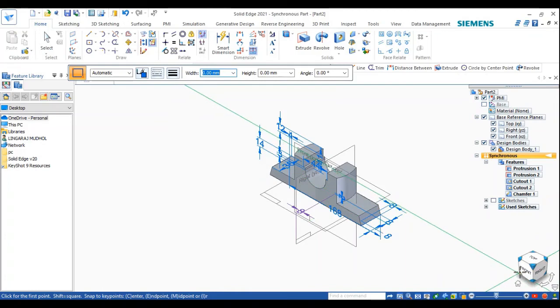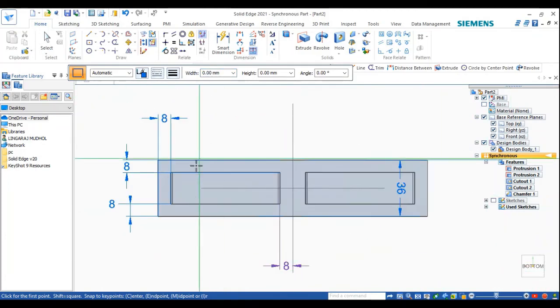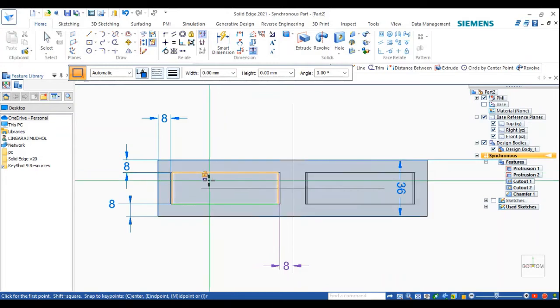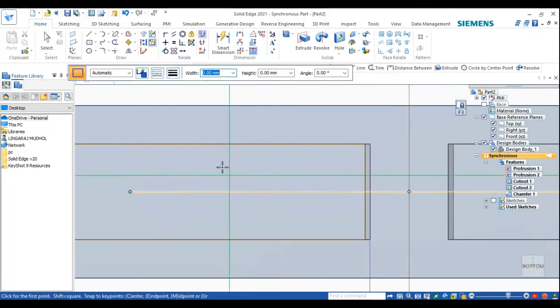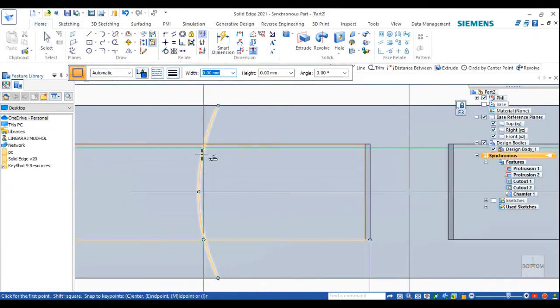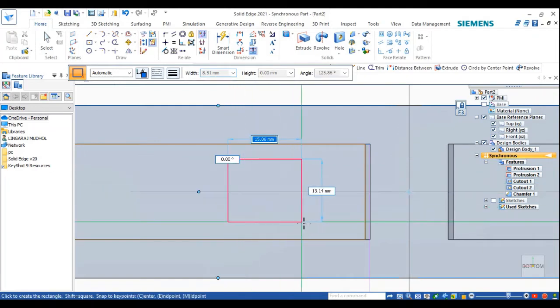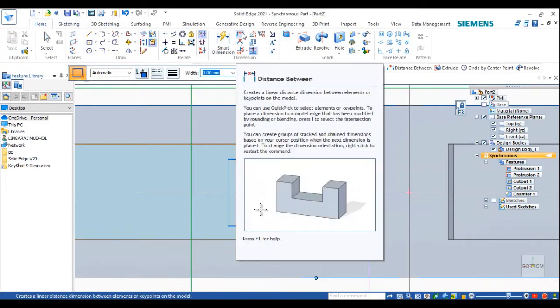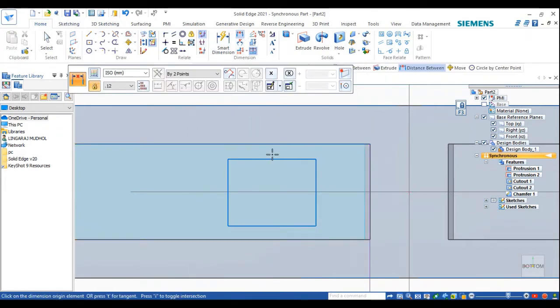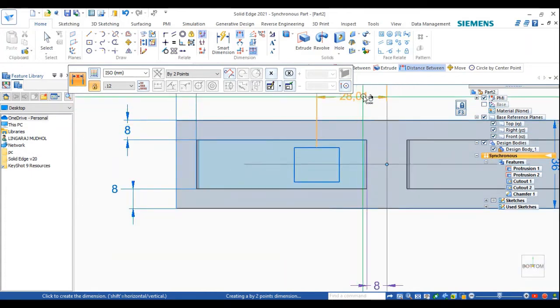So again, we should make a square cutout inside this. Again, go to the bottom part, click on this surface. Okay, take off any dimension. They have given the dimension of 20 mm square. First, we'll measure the center point and the axis length.